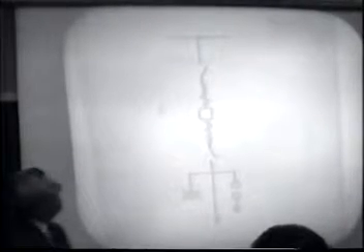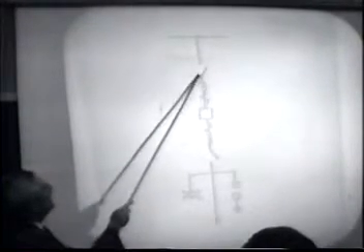Sketch number 1 is an example of a very simple single line diagram, and this particular sketch shows details of the power circuit only. As you can see, we have shown the electrical relationships of the different components: disconnect switch, circuit breaker, disconnect switch, potential transformer, lightning arrestor.